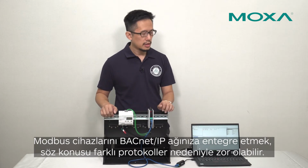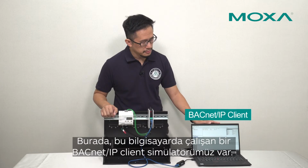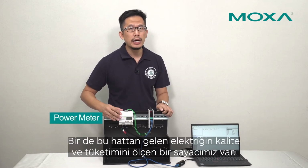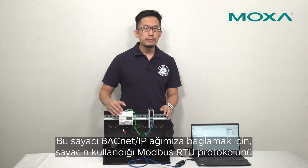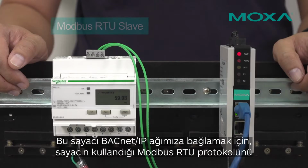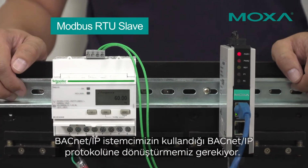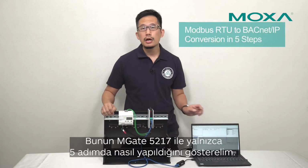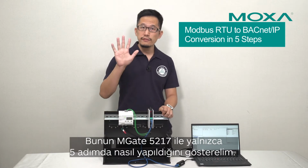protocols involved. Here, we have a BACnet IP client simulator running on this PC, and we have a power meter that measures the usage and the quality of the power coming through this power line. To connect this power meter to our BACnet IP network, we have to convert Modbus RTU protocol, which the power meter uses, to BACnet IP protocol, which our BACnet IP client uses. I'm going to show you how to set this up with the MGate 5217 in just 5 steps.